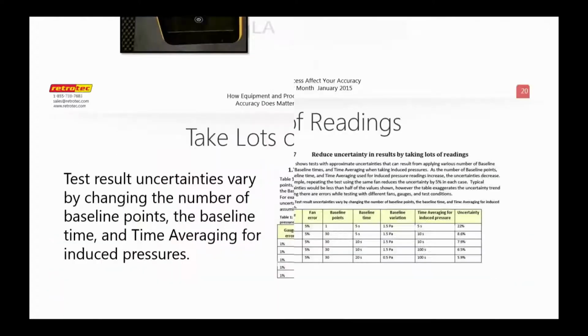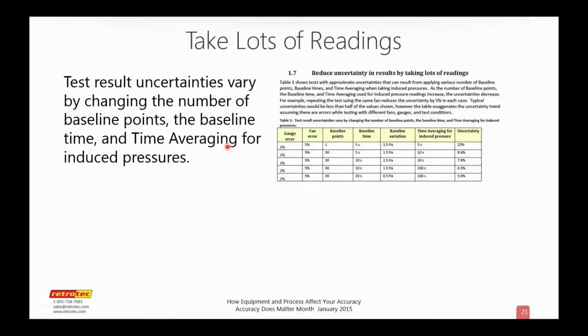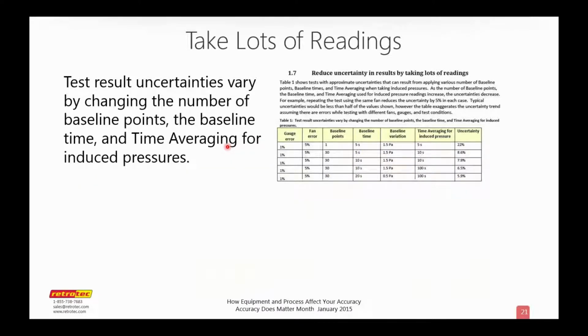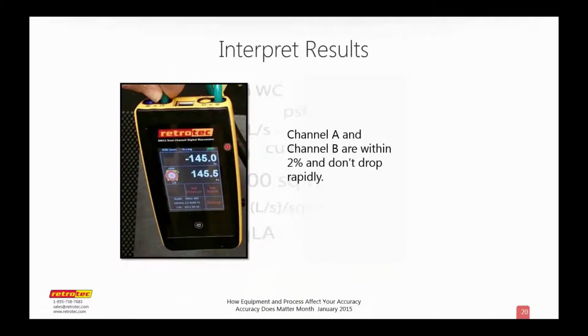Yeah, if you do have a problem there, the first thing you would do is, if you've got the green going to the negative of channel A and the positive of channel B, that's why one channel is reading negative and the other is reading positive. Oh. You're actually checking the negative side of one channel to the positive side of the other. But if you do have a difference, and one of them is out by quite a bit, then the first thing you do is just try another tube.